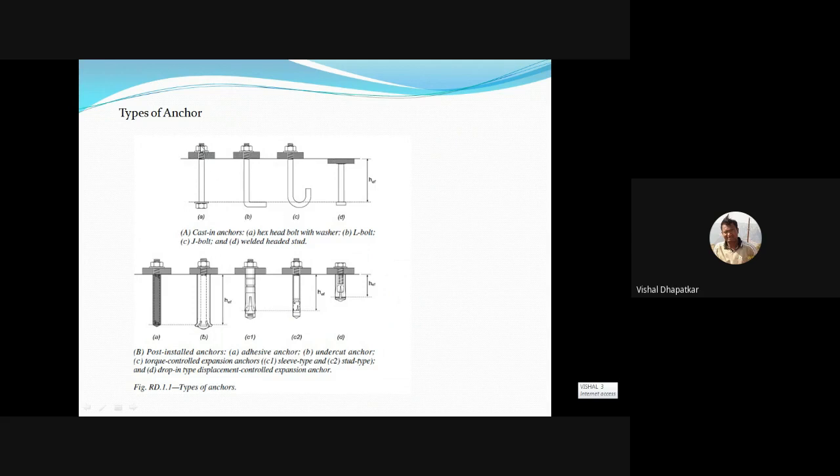The first bolt is used for heavy equipment or structural column fixing. Like the warehouse we have designed, if you want to fix it along with the pedestal, then this kind of bolt is used. It has a specified length which will be embedded in the concrete, so that it will give you sufficient tension capacity.